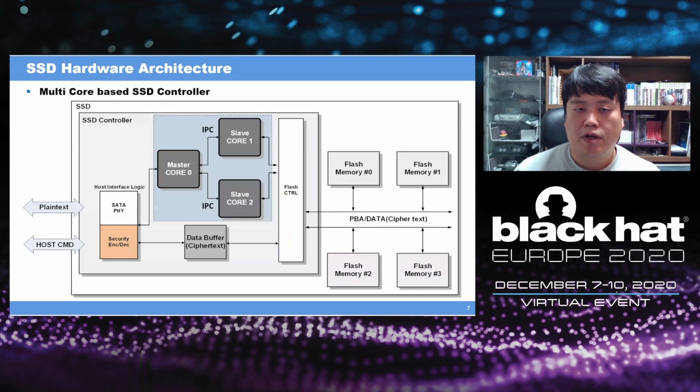Let's look at the commercial SSD architecture. The SSDs are equipped with several low-power embedded processors such as ARM and ARC. Generally, mid-range SSD controllers adopt a multi-core architecture to maximize I/O parallelism. So if they should support more channels, the controller might be made of more cores as well. A single-core based controller contains all the middleware in a single core.